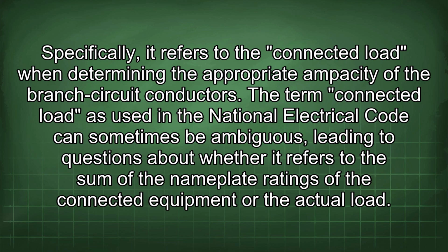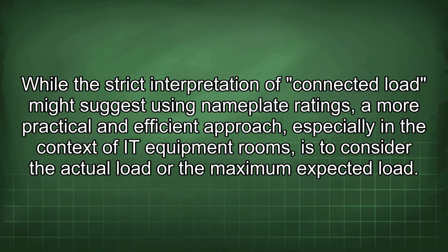The term connected load as used in the National Electrical Code can sometimes be ambiguous, leading to questions about whether it refers to the sum of the nameplate ratings of the connected equipment or the actual load. While the strict interpretation of connected load might suggest using nameplate ratings, a more practical and efficient approach, especially in the context of IT equipment rooms, is to consider the actual load or the maximum expected load.